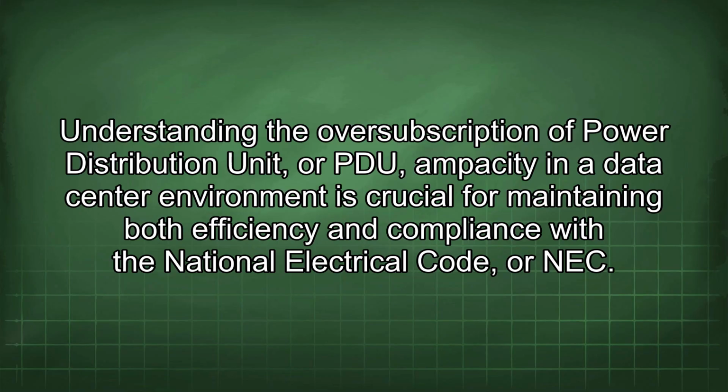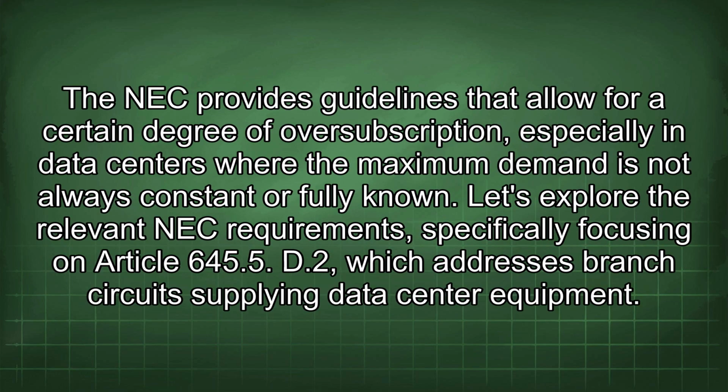Understanding the oversubscription of power distribution unit, or PDU, ampacity in a data center environment is crucial for maintaining both efficiency and compliance with the National Electrical Code, or NEC. The NEC provides guidelines that allow for a certain degree of oversubscription, especially in data centers where the maximum demand is not always constant or fully known.